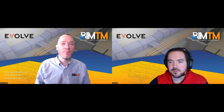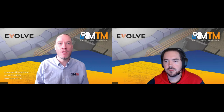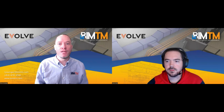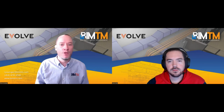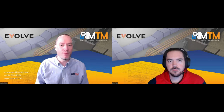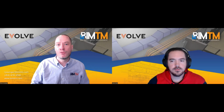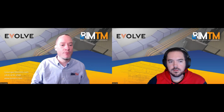Right. And there are some things you can do to make it easier with a point cloud. You can clean up a point cloud, because you're going to capture a lot of things that you don't need. With things like reflections or mirrors, you're going to get some points where the data isn't accurate, so you can clean that up a little bit. You can also segment your data, so you can identify your different views before you import it, which makes it a little bit easier. So there are certainly different things you can do to make it more user friendly. Down the line, we can explore discussing further all the different ways that you can work through those challenges.